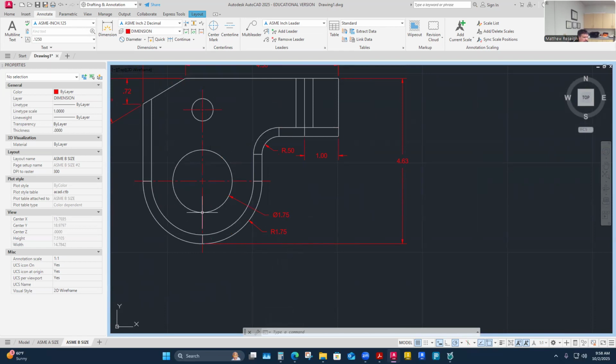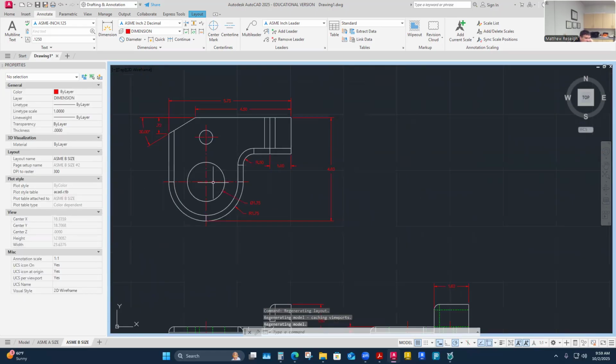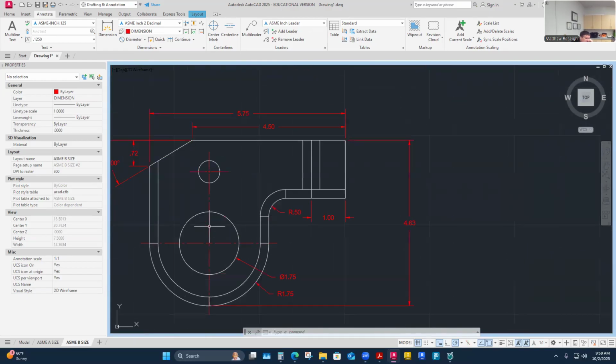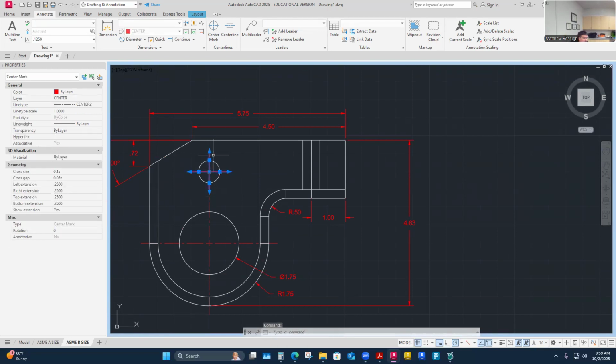Now let's capture the location of that feature, the hole. So its location, I'm going to define here, and I've got the two datums here to pull from. I've got the backside surface. I'm going to pull that dimension, and I'm going to pull the right side surface over. And I really only need to pull it over. I'm showing the concentric nature of these two holes, at least, or these, not concentric, sorry. I'm showing that there's vertical alignment to these two holes. So I only need to dimension over to, I'm probably going to end up pulling this one out like this.